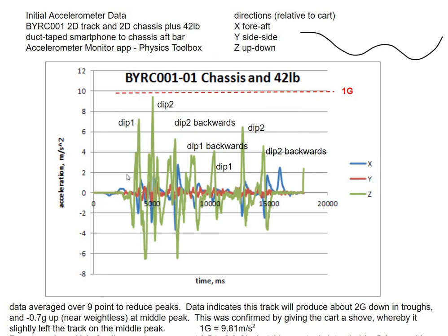Anyway, sometimes you have to filter the data, because sometimes accelerations are funny. It'll track an acceleration that's less than 200 milliseconds, but your body can't react to that. It's too quick. You can't feel that. When you jump off a step, you can experience 15 Gs, I've heard, but it's for such a short time that your body doesn't really react to it.